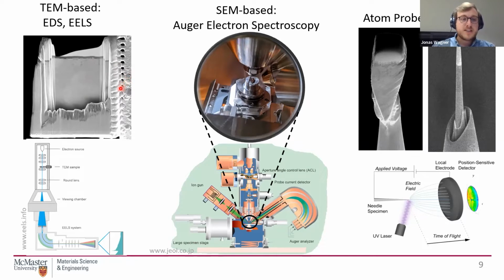Once that is done, it is inserted into our TEM here, and we turn on the beam, and we can record the EDS signal from detectors, usually inside the column, either before or behind the sample, or both sometimes, while the primary beam is conducted towards the bottom of the instrument, where we have an electromagnetic prism that projects the beam on a screen, and that is how we get our EELS spectrum.